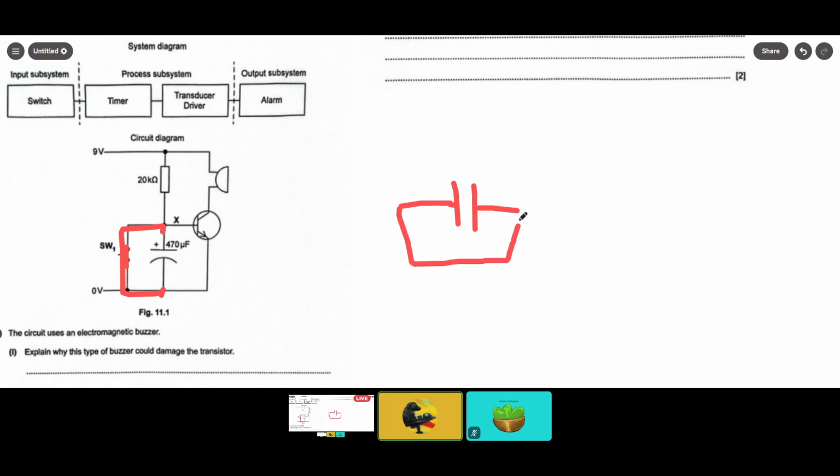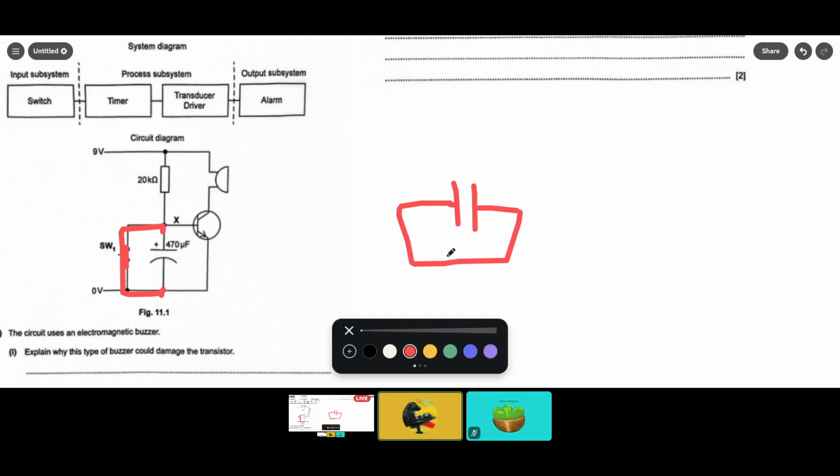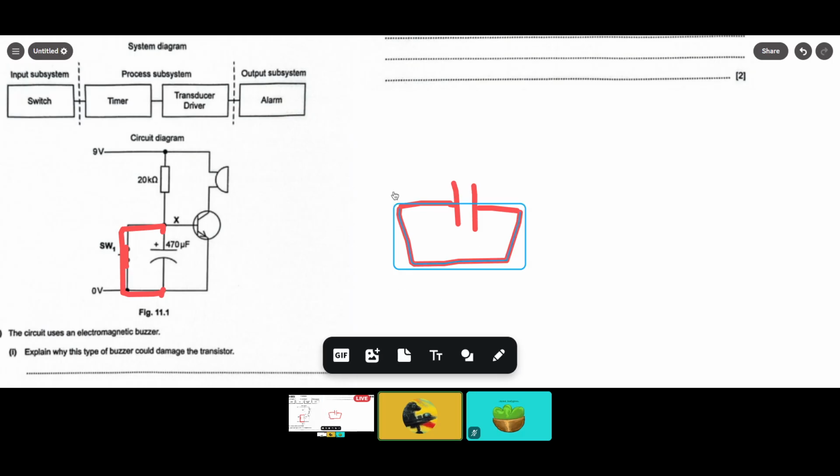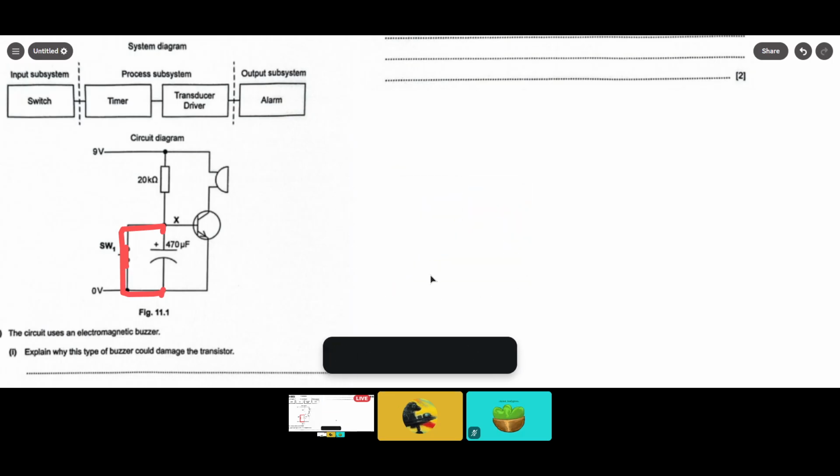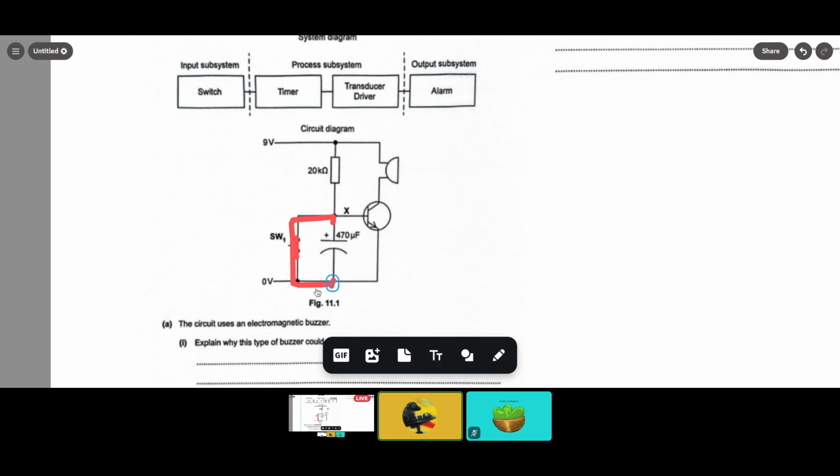When you connect it to itself, it's going to start dissipating that voltage, that energy. If you leave it for a while, the stored charge will be 0 volts. So basically, if a capacitor connects to itself, it will discharge. And this switch, when closed, achieves that, because we can see it short circuits the capacitor to itself.